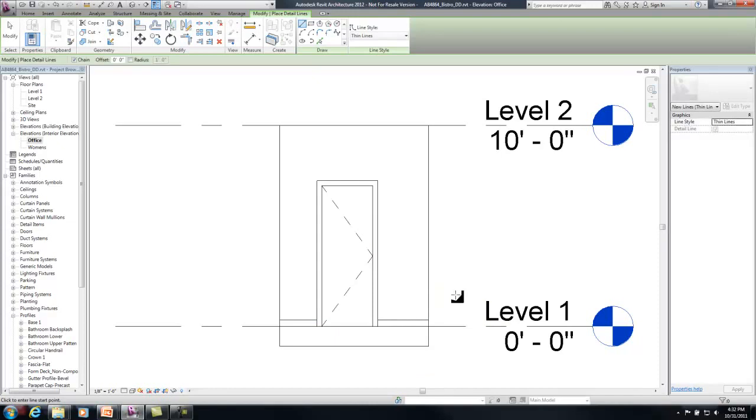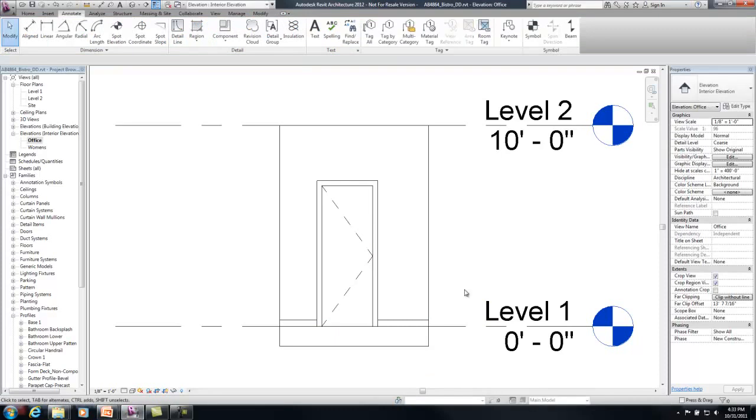The 2D elements give us a very simple way to represent the base, which is helpful when it's plain like this, particularly on anything that is 1/8 inch or less in thickness, like our plain vinyl base here. It's unlikely to go through multiple design variations, so there's no need to have it modeled in detail. Also, when you go to other elevations or side views, you don't want to see the thickness of those elements either. So those again are reasons that you may want to choose 2D elements to represent some of your items